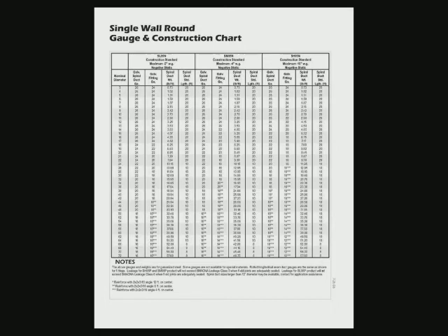Not only that, the higher static pressure construction is a heavier gauge, and in some cases we're going to have a little particulate running through the system. In the case of diesels, for example, you've got diesel soot running through the system, which is highly abrasive. We don't want to wear the duct out just because of the dust, or in this case, diesel particulate running through it. So that heavier gauge material makes it a little more robust.